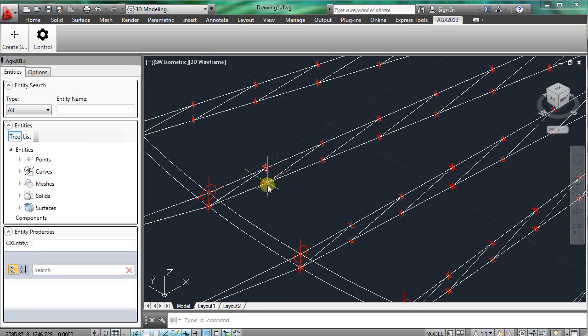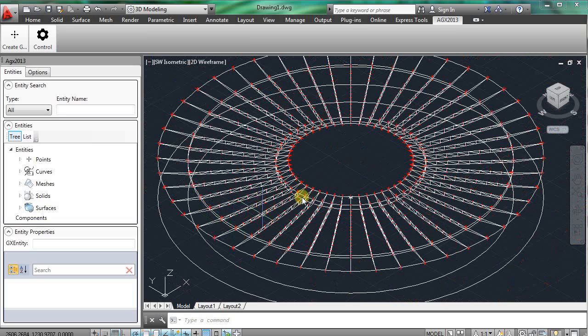Now to create a line vertically down or vertically up, we just do the exact same thing. Start and end point, and we use the defaults 0 and 0. And there we go, we have a replication of the truss at least.